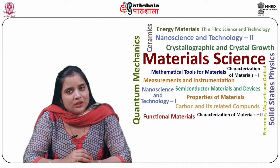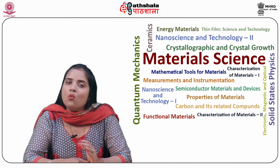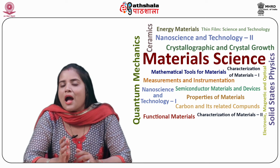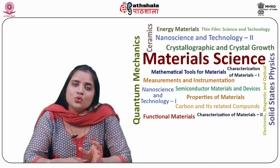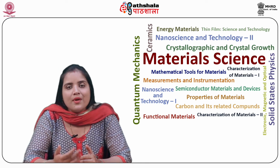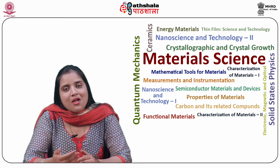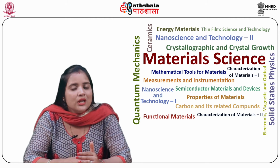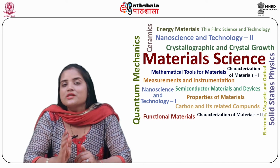The most commonly used material is silicon, which is used in two layers. One layer is doped with boron and the other with phosphorus. The chemical electric charges in the two layers are different and subsequently both drive and direct the current of electrons. An array of solar cells is used to convert solar energy into a usable amount of electricity which is in DC form.